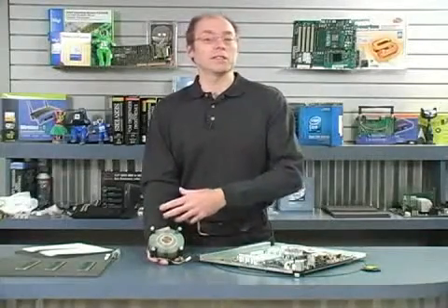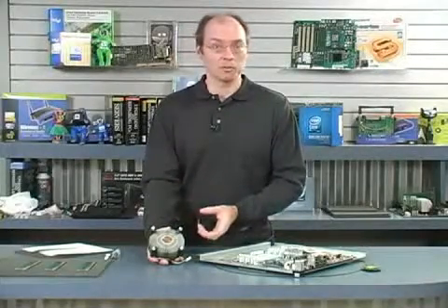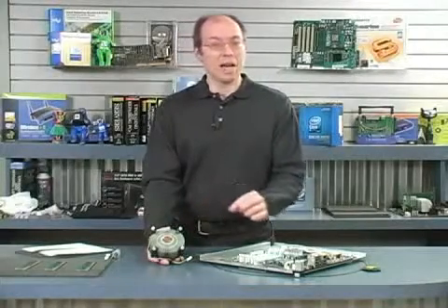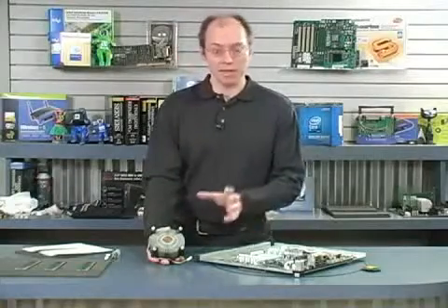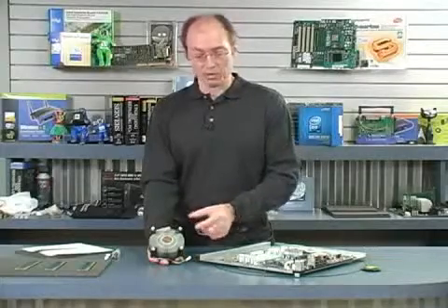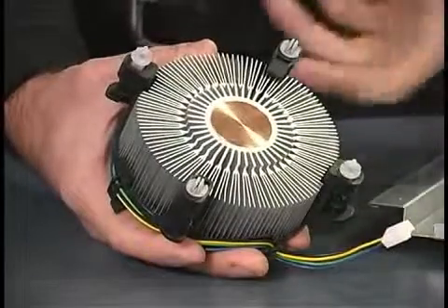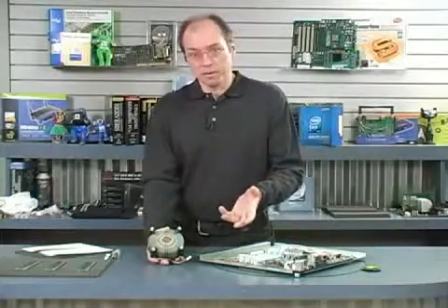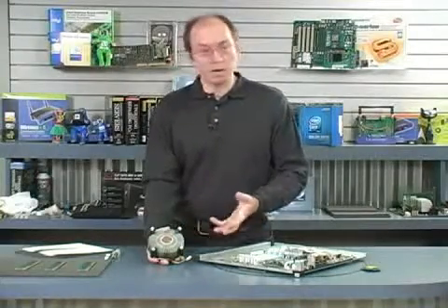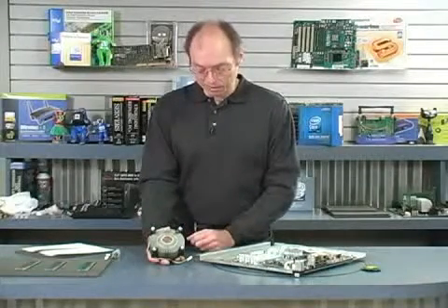So why don't we see heat sinks that are all copper? Well, the problem is copper is expensive. It's a lot more expensive than aluminum. It has twice the thermal conductivity of aluminum, but it also costs from 3 to 9 times more, depending upon whether you're going by weight or volume. So the compromise is that many heatsink manufacturers will have a copper core, like you see on this one, and then surround it with fins made out of aluminum. Depending upon the performance nature of the heatsink, some might be all aluminum, or some might be all copper. In any case, those are the different types of metals that you'll see.